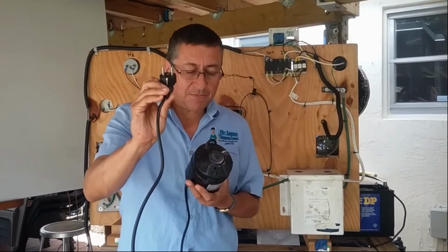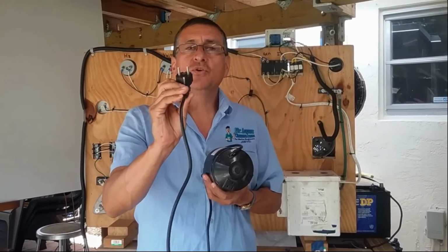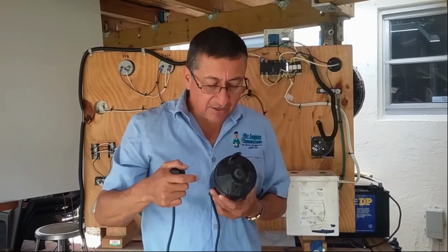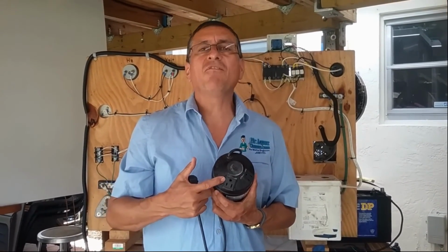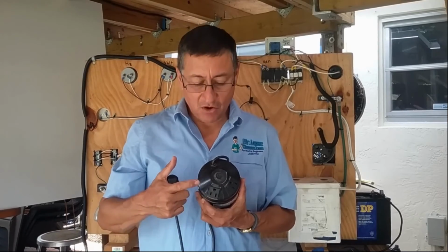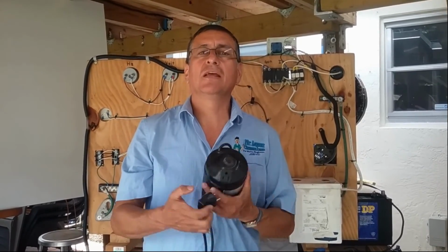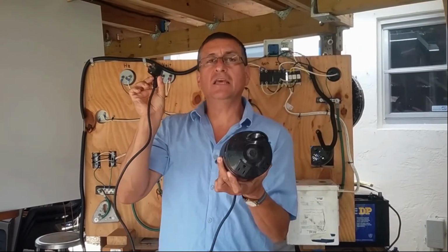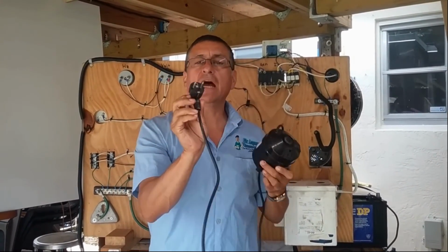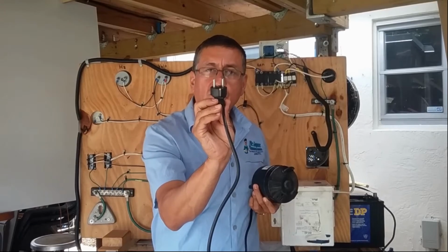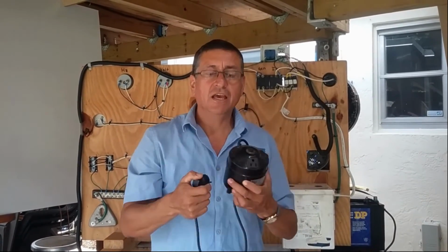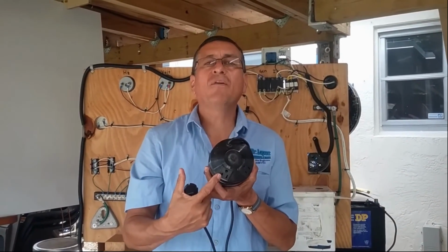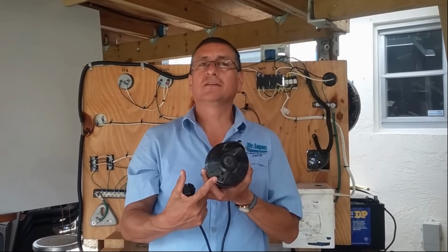And with this step-down transformer, you convert 230 volts, 50 hertz into two outlets, 115 volts, 50 hertz. 115 and 115. You have a European boat, and you install this step-down transformer, and you convert this phase, 230, 50 hertz, into two outlets, 115, 50 hertz.